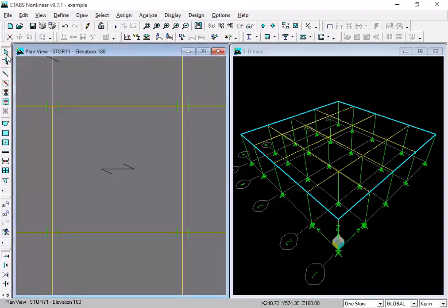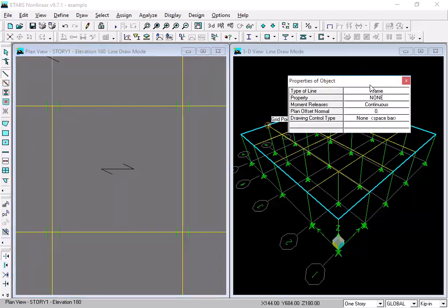So it is better, look, if I begin from the start, when I click on this draw lines, a panel appears, and there is a second option here where you can select what you want to draw, and you will see that right here these are sections which were available in your steel manual, right? W14, 50, 257 or whatever. In here there is an option called none. Just come here and press N. When you press N, it will take you to none line.